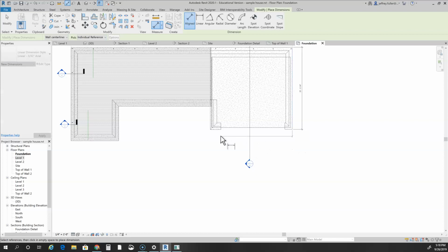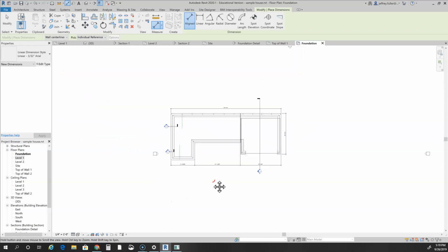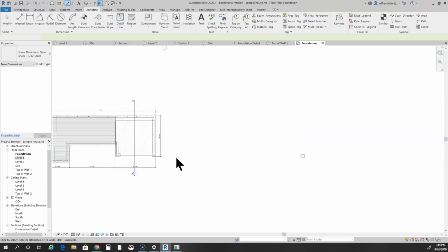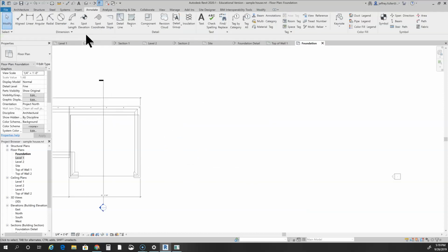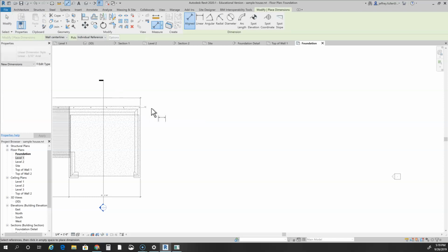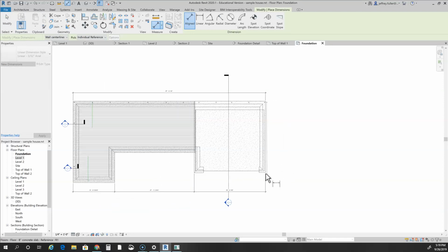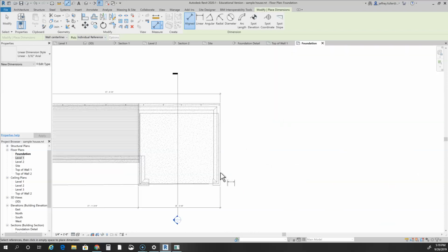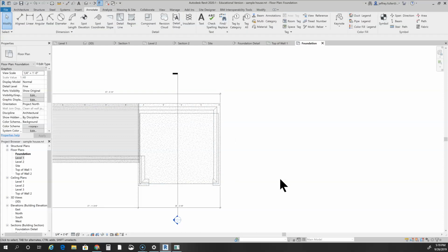And again, when we're dimensioning our foundation, we want to get all the breaks, all the corners. Okay. And, you know, about this far, make sure you use your furthest extending wall to gauge your distance with. Just make it very similar to that one. And we actually should have, let me delete that one. I'm going to redo that one. Okay, because we're supposed to do this, so I have to carry it on until I get this one. Oops, I did something. Try that again.